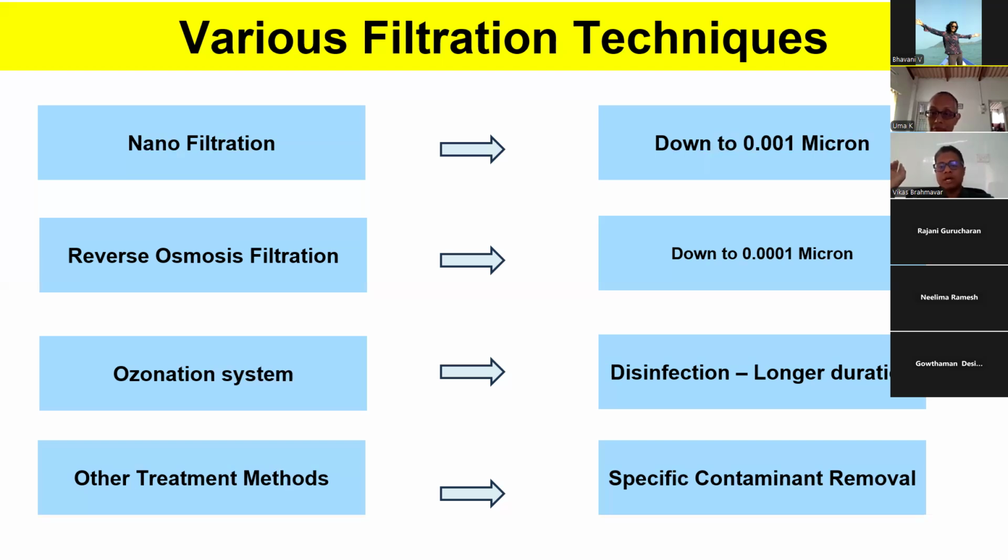So we should be aware: if it is 7.5 or 8 pH water going in, then generally the salt reduction is not a problem. The pH also would not have been reduced drastically. So we should worry about pH reduction more than the salt reduction.